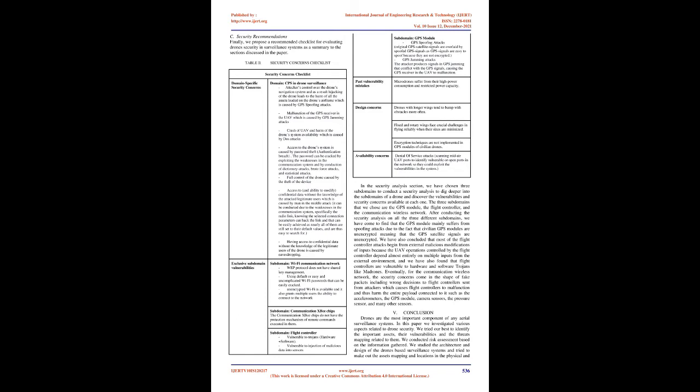The attacker needs to know the following communication parameters to communicate with an XB868LP chip: PAN ID, network ID, baud rate, channel, DH, high destination, address, and DL, low destination, address. However, the PAN ID, baud rate, and channel for each UAV are all set to default values if the user did not change them. Also, the XB868LP chips respond to broadcast packets sent within their network, hence the message of acknowledgement for the broadcast includes the sender's address, thereby exposing all available devices within the network.